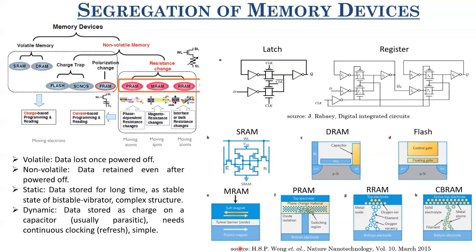So the problem with MRAM is that the resistance ratio between the parallel state, when the magnetization is parallel, and the anti-parallel state, when the magnetization is non-parallel, is very small. The maximum ratio between the resistances RAP and RP, the maximum tunnel magnetoresistance ratio, is 800%. That is, 8 times. So the maximum ratio of the resistances has been found to be only 8. Typical values are 2 to 3.